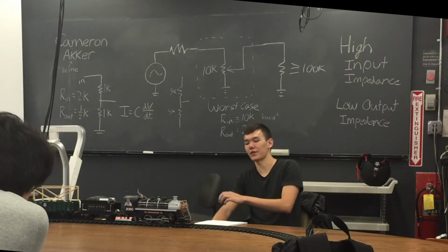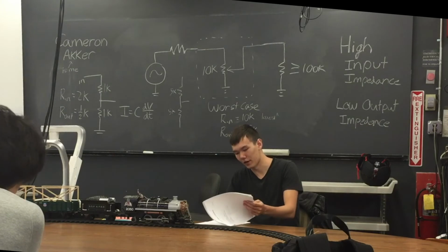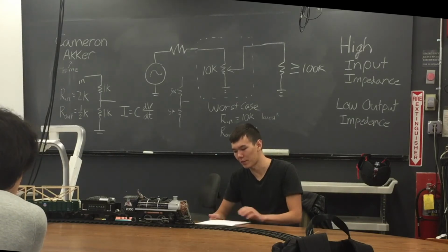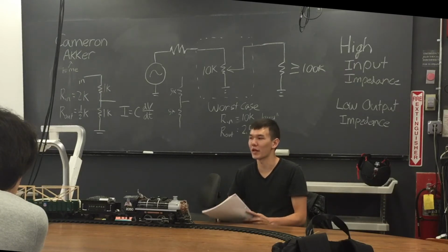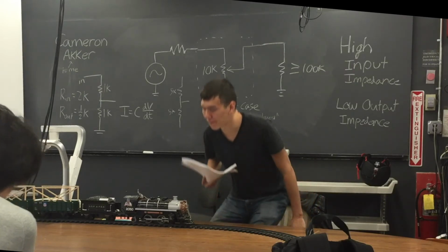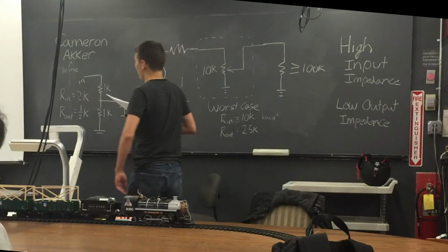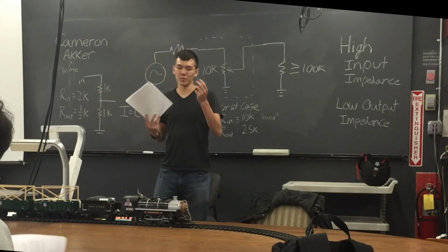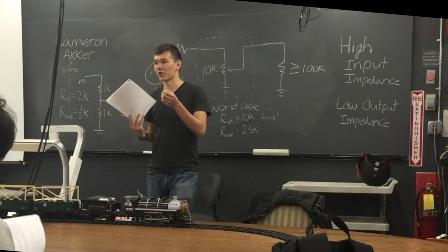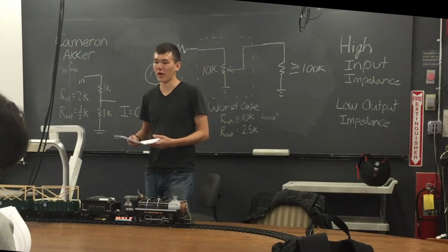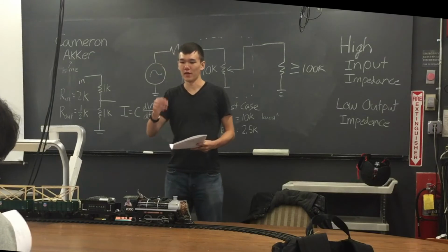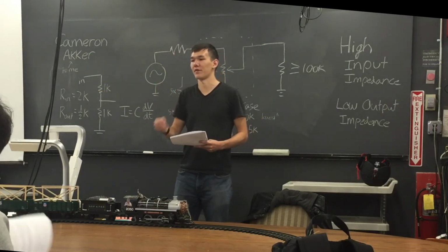Oh, so capacitors. I can talk about capacitors because that's something that is relevant beyond just the high pass, low pass differentiator integrator. You're going to want to use decoupling capacitors a lot. The reason for that is basically, a capacitor holds some charge on there, and when there's an aberration from the norm, the power supply flips or something draws a lot of current at once, the extra charge just sort of helps save that.